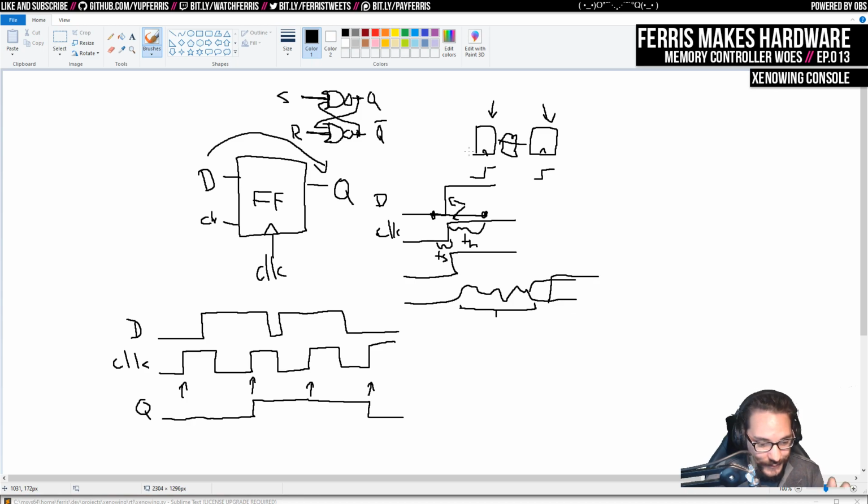And the other thing, coming back to this reset stuff, is that when you push that reset button, that's not going to be synchronized to this clock, because it can't be. It's an external signal, and it's going to happen when you push the button. It's probably going to bounce a lot when you push the button. So essentially, all external signals that come into the chip like that, we need to synchronize them to the clock.